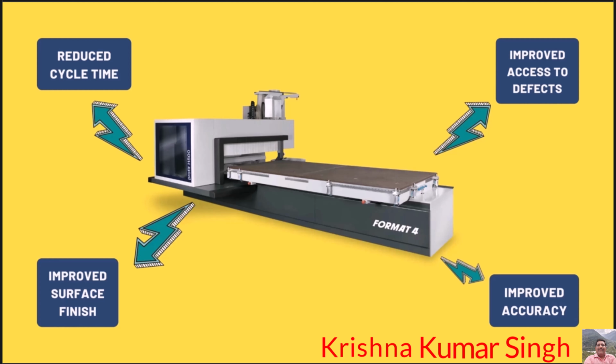In addition to time saving, improved accuracy can also be achieved as positioning errors between setups are eliminated. Improved surface finish and tool life are achieved by tilting the tool to maintain optimum tool to part contact at all times.